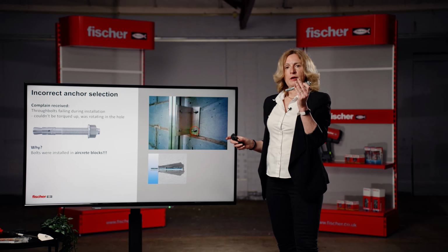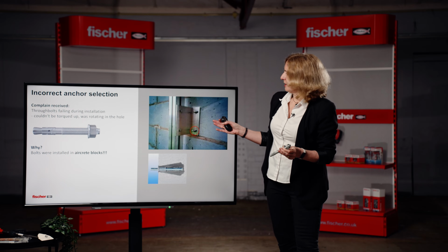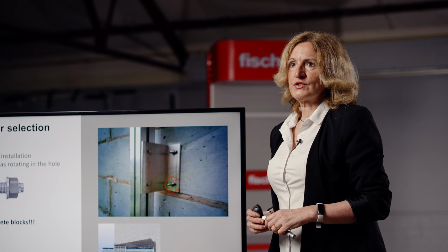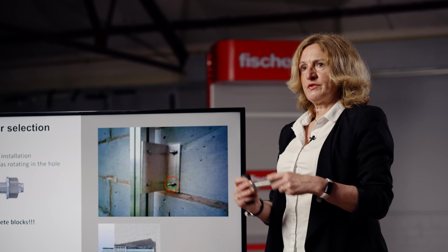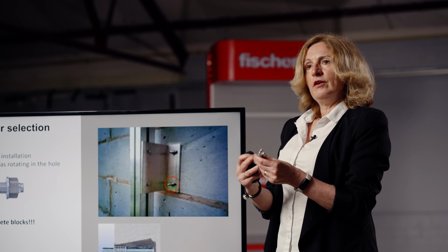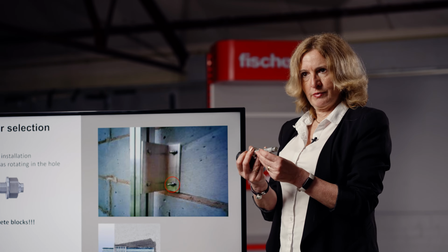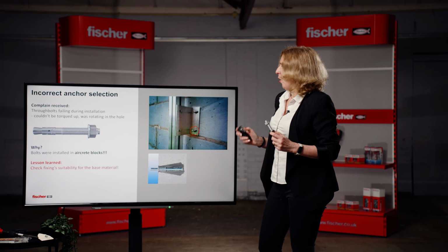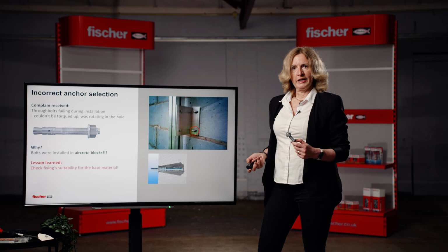This product is approved and suitable only for concrete, and the end user was using it in masonry, and what was even worse, it was aerated block, a very soft material. So of course, when they tried to expand the anchor, the fixing was just crushing the soft material and spinning. So lesson learned: always check fixing suitability for the base material you are installing into.